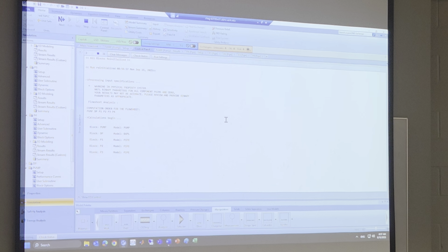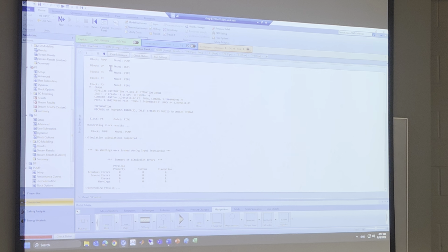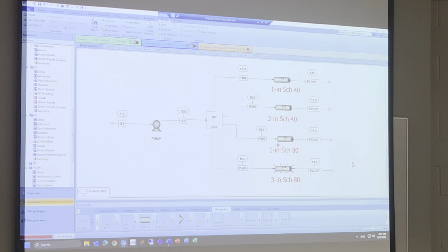Can we use 1-inch schedule 40, 1-inch schedule 80, 3-inch schedule 40, 3-inch schedule 80? So if you look at here, we got one error, means something is not working. If you check here, which piping system is not working? Page, Brian, who can see? 1-inch schedule 80 is not. 1-inch schedule 80 not working, right? So as you can see, if you look at 1-inch schedule 40, pressure drop is already 11 atm. If you use 1-inch schedule 80, this system is not working.